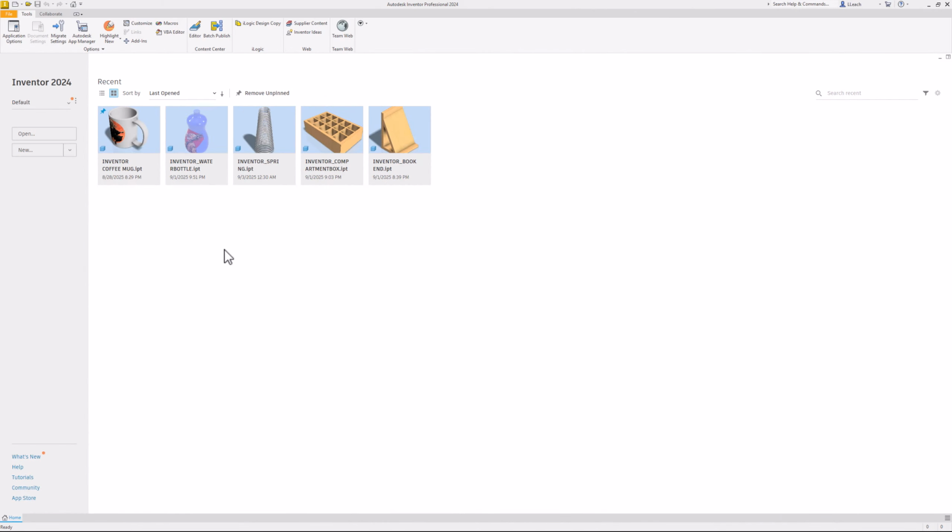Hey, welcome in everybody. In this video I am going to again show you how to use the coil tool, but this time we're going to be creating a silly straw. So it's basically kind of similar to creating that spring that we did earlier, but we're just adding some end pieces to it.